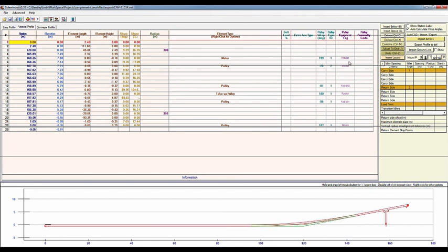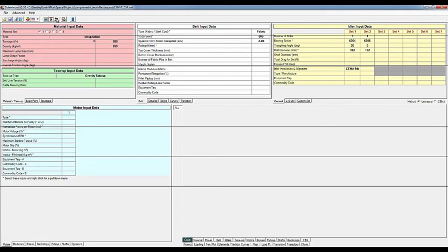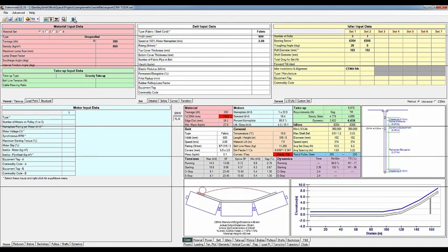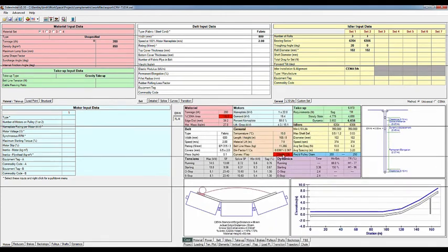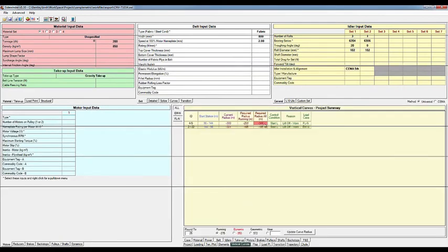Calculations are conducted against the existing design and performance is checked. Sidewinder highlights some areas of concern. The belt width is incorrectly sized and the radius is too large for the capacity of the belt. Modifications to the design are made here until there are no more warnings. The changed data is exported back via data file.